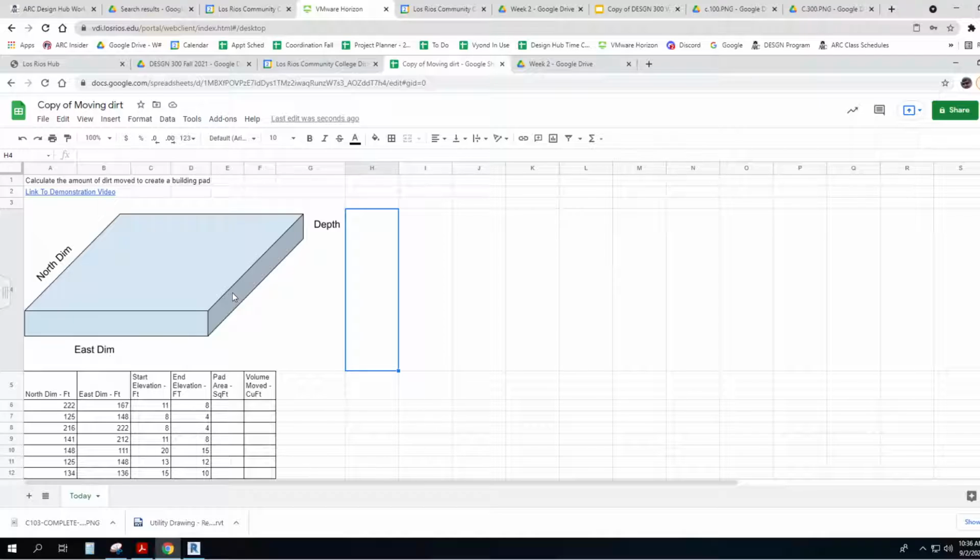So the architect or the civil engineer will say, I need a certain structural strength of the dirt. Believe it or not, dirt has a certain compressive strength. And you need to do something to the dirt in this area to make it just right. And that's usually called compaction, which we're going to talk about next week.